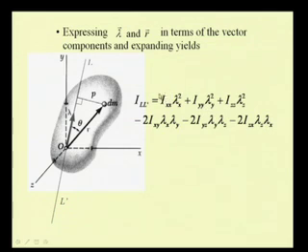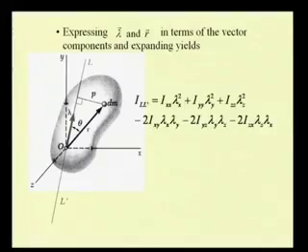So, these quantities, that is Ixx, Iyy, Izz, Ixy, Iyz and Izx, are nothing but the inertias that are known with respect to the x, y and z axis. So, if we know the inertia tensor, all these 6 values are known to us, and if we know the direction cosine of the axis for which we are interested to find the second moment, then we can find these values, that is ILL, in terms of these products of inertia.